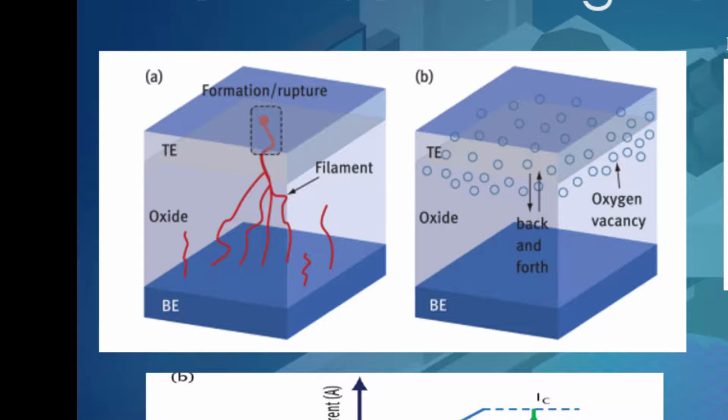The metallic filament grows until the top electrode and bottom electrode are connected, which indicates a low resistance state, and it can be reversed by applying a negative voltage, which is the case for the high resistance state. A simple explanation of ReRAM is that when an electric field is applied, it removes atoms from the oxide material and becomes metallic, which creates a low resistance state. By applying a negative step voltage, it brings back those atoms, creating a high resistance state.